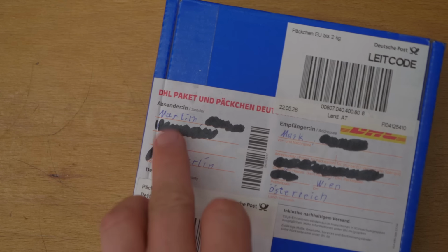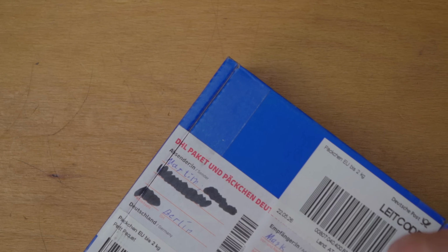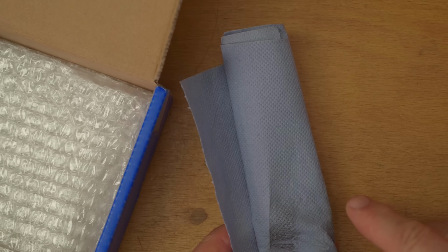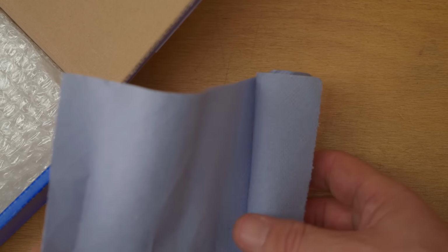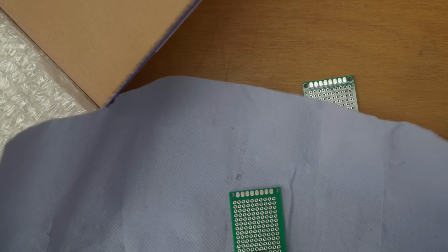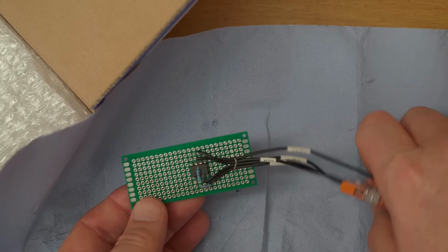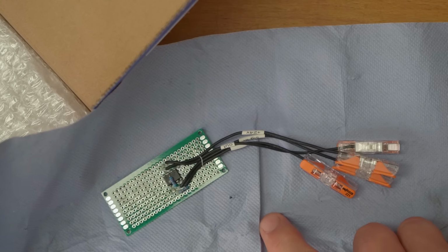Now this is coming from Martin in Berlin, and he's been talking about this because he's got the same lathe as me, and he had a better solution for getting the spindle control working. He used the feedback of motor speed from his VFD to calculate the gear ratio. I think his VFD outputs a signal in milliamps or so, whereas mine puts out a voltage signal and would need scaling. So he whipped up this little op amp, which he said should do a good job of scaling my output signal for my VFD. So I'm going to have to wire that up and give it a go.